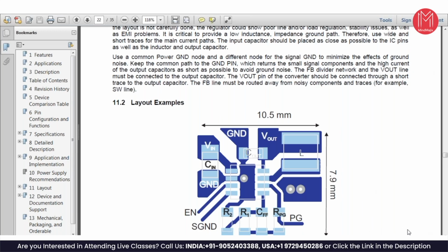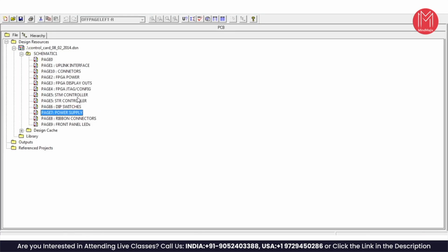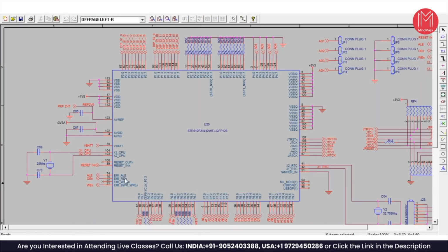That's for the signals. What is the signal ground? Let's say if you look at it, this is all power ground. But if you take a controller or something, any ground that you see is the signal ground. It's not the power ground. That means you're running high speed switching and all.